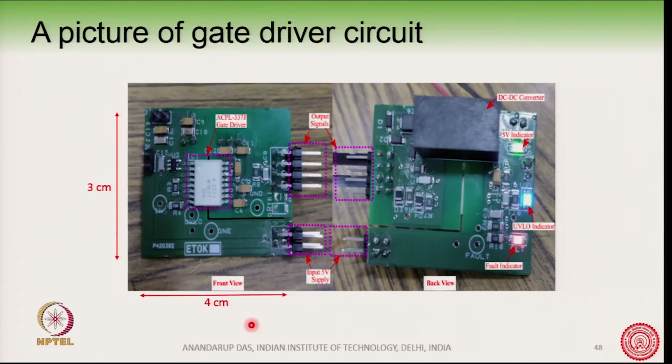This gate driver board has many protection features, as this driver IC also provides. It also has an isolated DC-DC converter, and there is also a cut on the PCB so as to provide a physical isolation. We have been using this gate driver board to drive the SiC MOSFETs, but it can also be used for driving IGBTs or silicon MOSFETs.